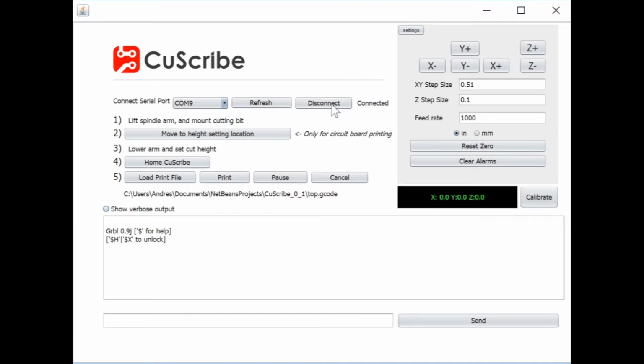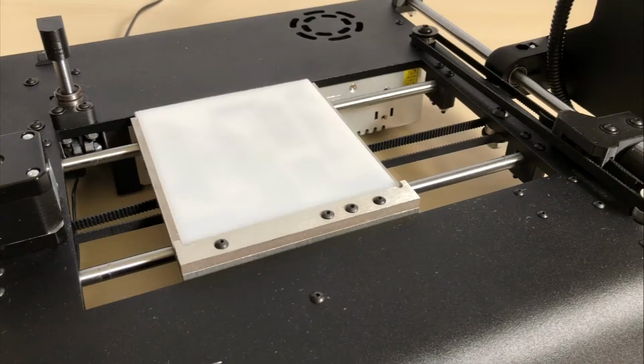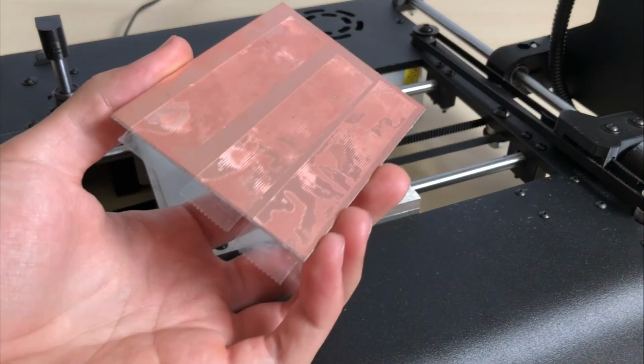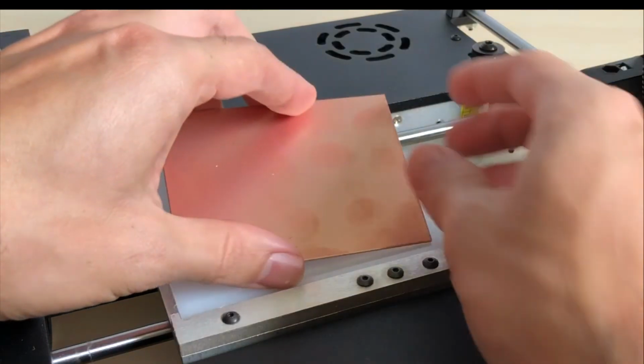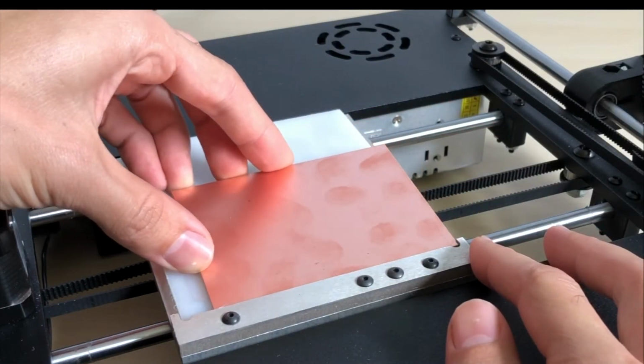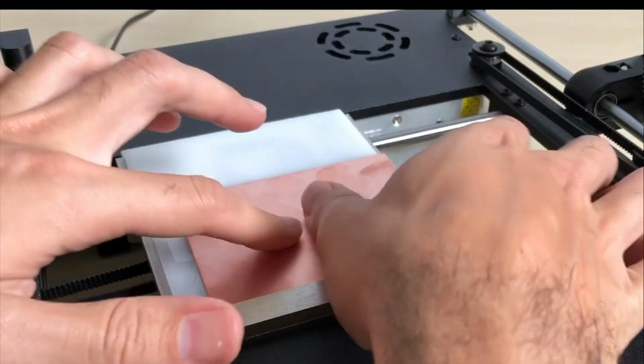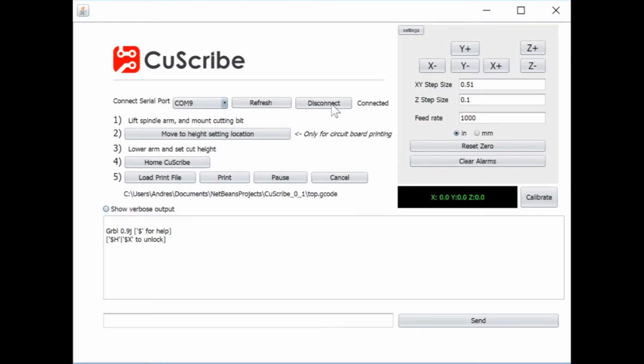Before continuing, make sure your spoil board is clean and any defects are sanded off, so that we can stick our copper board to it. For bottom traces, we want to stick our copper board to the right side of the machine's bed using double-sided tape. Make sure the edge of the board is properly lined up with the print bed. Now we follow the steps outlined in the CuScribe control software.